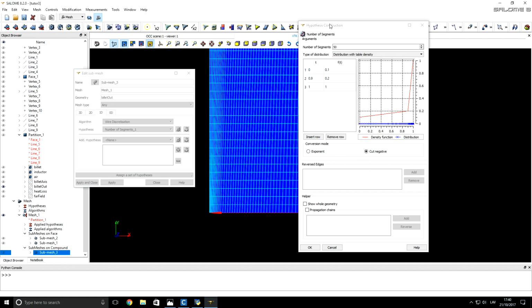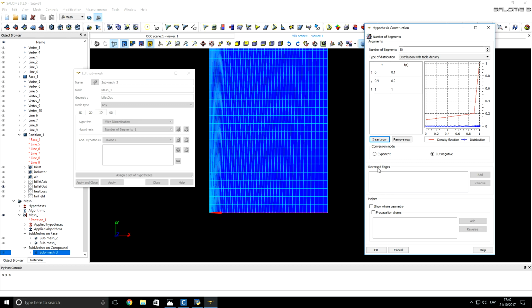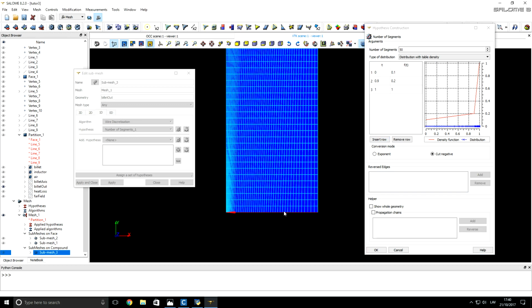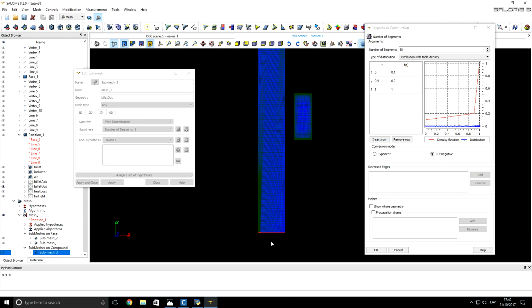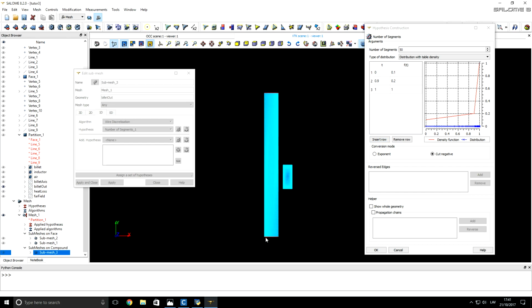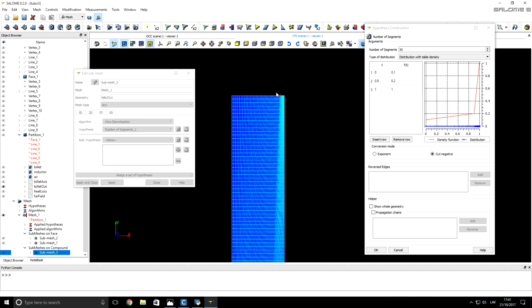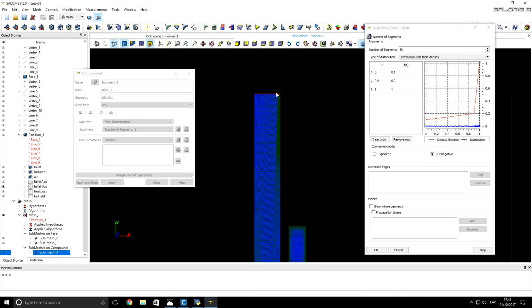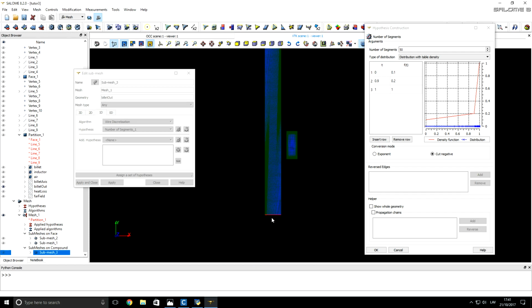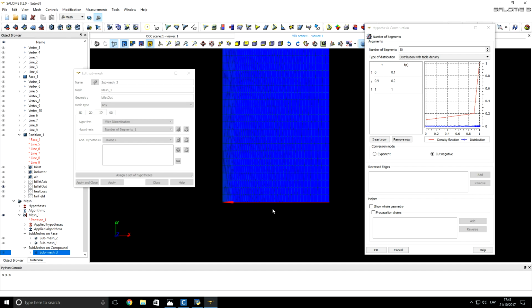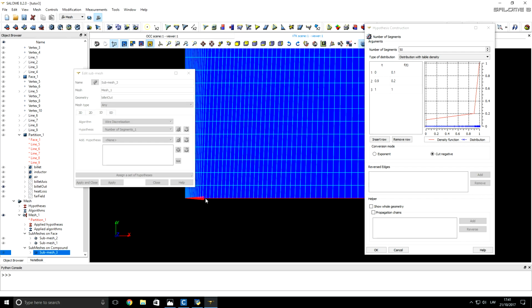You can see that there is a window called Traversed Edges. Also, you can see in our Salome window that on our billet, here on the bottom and here on the top, there are 2 arrows, and those arrows have opposite direction. What we need to do is click on this lower arrow here on the bottom. We have to click it, select it,